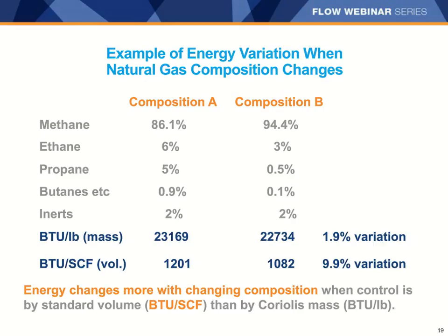The other thing that you'll note is that ultrasonic meters are very commonly used. Ultrasonic meters are quite popular in natural gas custody transfer, and Coriolis meters and ultrasonic meters are both growing in use in today's environment. And you can see ultrasonic meters have almost caught up with differential pressure meters, at least in this poll, in their popularity.